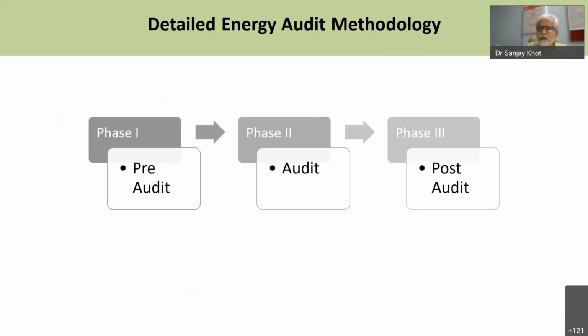Once you get that understanding or work order, immediately you should ask for some data which is required to plan that energy audit before reaching the industry. That all comes under the pre-audit. And once we are prepared with the baseline calculation, energy bills, invoices, and what type of instruments we need to use inside the energy audit, accordingly you will enter phase 2, where actual measurements are taken.